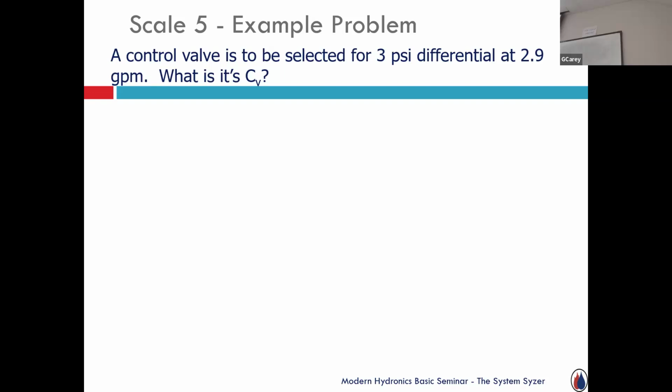I've got this control valve controlling the flow, maybe through a heat exchanger, and I'm looking at the downstream, the outlet of what I'm trying to measure, what I'm trying to control. When that valve goes to throttle, I want to have an impact on the output. If I'm saying I'm starting to get too hot, then I want that valve stroke to take place. It better have an impact.